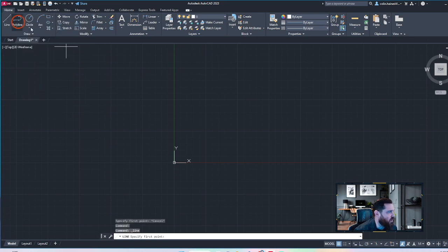So we're just going to draw our little square again. With absolute coordinates, we're going to start at 1, 1, enter. Now we're going to go 1 over on the X axis, but we're going to type that a little differently. We're going to type in @ symbol 1, and then the angle symbol, which is also the greater than symbol, or, if we were teaching elementary, the alligator eating the number that comes after it. Because we're going directly to the right, that's going to be an angle of 0.